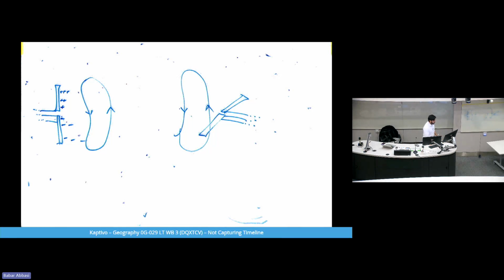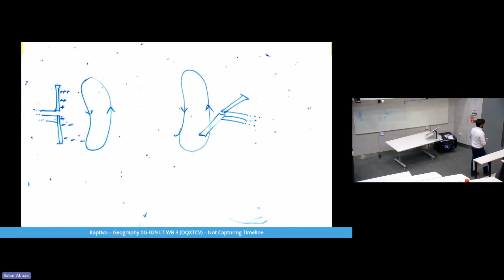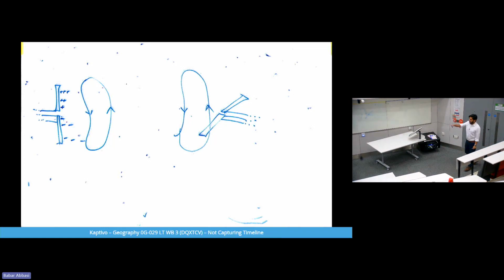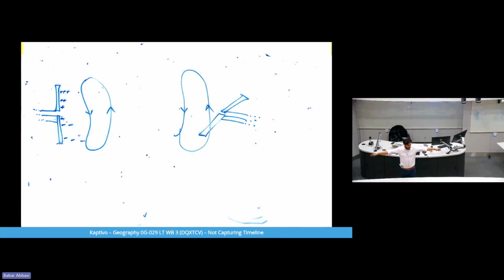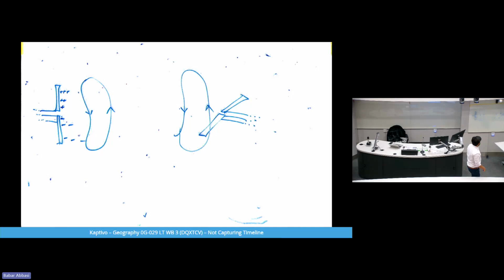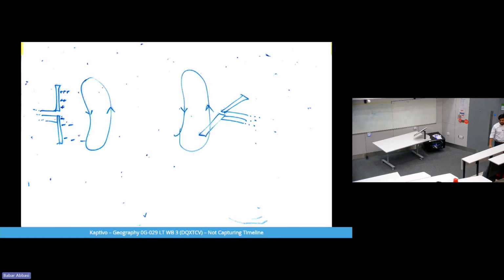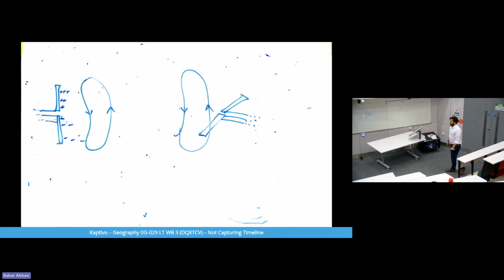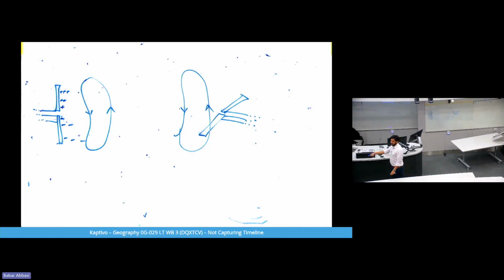So we have two polarization components. One is horizontal polarization, one is vertical polarization. This is true for our linear antennas. So if you are building a simple dipole antenna to receive television signal, and that antenna is like this with multiple knobs, then it means that it is receiving a horizontal polarization component only. Okay, but now our devices, our mobile phones, these sort of consumer electronic antennas, have multiple polarization components, so they are capable of receiving energy in any polarization basically.